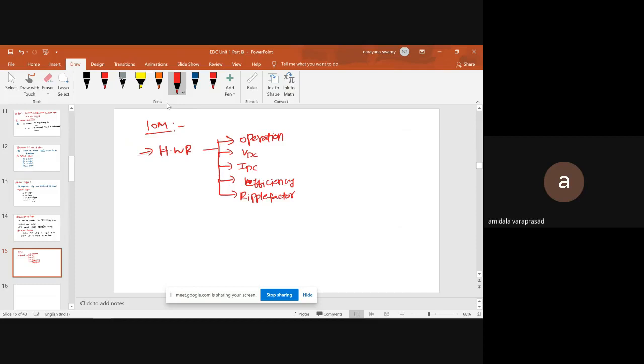We know the circuit diagram, everyone knows. For half wave rectifier, here we have a step down transformer. Here it is V0. Here is the signal we apply. This is a 220 volts signal. Here it is 12 volt signal. This is the circuit diagram. Plus minus. This is RL. Diode D. This is anode terminal, cathode terminal.